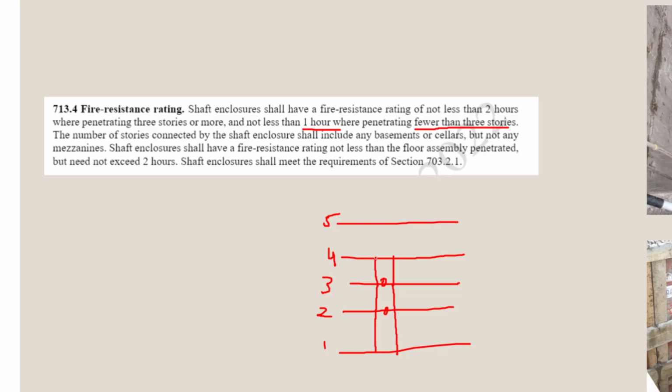Now, once we penetrate this fourth floor to the fifth floor, this whole shaft rating would have to be 2 hours, since we're penetrating these 3 floors here, which are the second, third, and fourth floors.